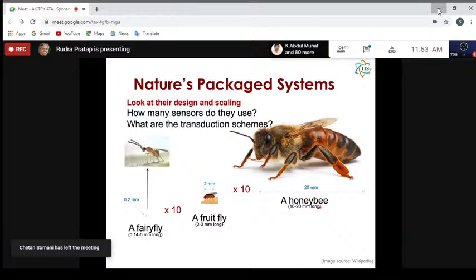A thin photoresist layer is coated, and you have a mask. This is a quartz or glass mask in which you have certain openings. Let's say that we want to pattern the silicon wafer such that I can make a cantilever beam on it. Okay, that's what I'm trying to do here.